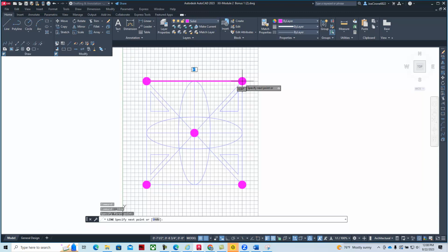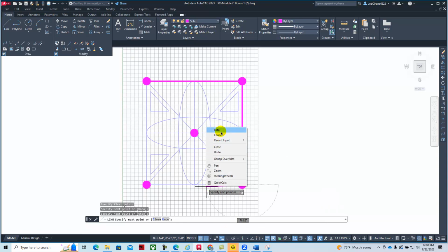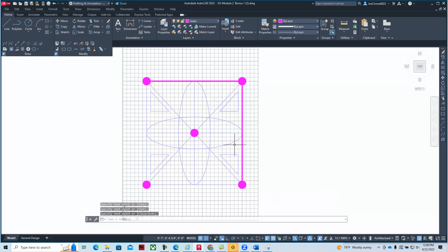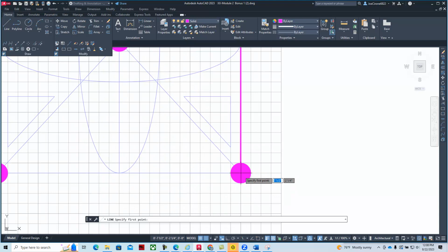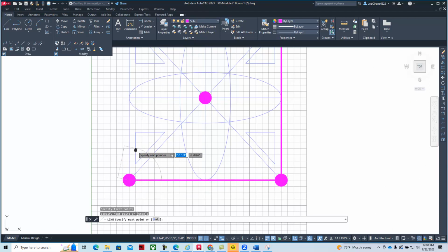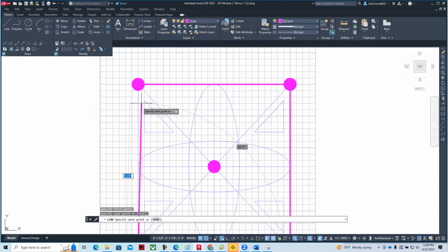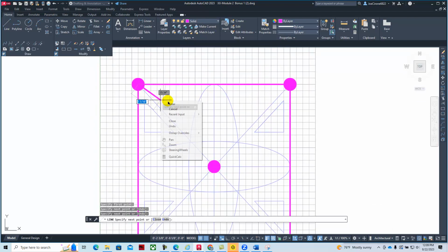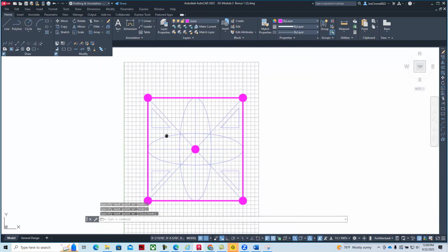And notice that the CAD system measures the lines that we create. And this is what's really great about working with CAD, is that it's very precise. And so I can create these lines. If I hit enter or right mouse click and enter, it will pick up the pencil. I can go back to the line command and get another line. If you need to zoom in, it's great, because you don't have to worry about magnification things. Nice thing about working with CAD is that you can make things really, really big, and it allows you to be more precise with their placement.